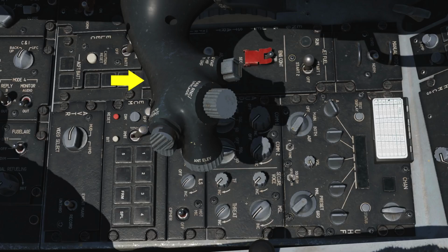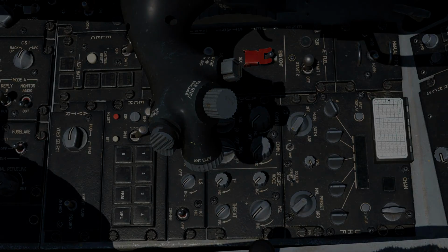HOTAS functions at the throttle include radio transmit switches, IFF interrogation control, a manual range and uncaged knob, radar antenna elevation, control wheel, a dogfight switch, as well as a speed brake and radar control cursor. In case of a deep stall departure, the pitch override switch allows you to command greater authority from the stabs to help get the nose pointed downhill so you can gain speed for control flight. The guards on either side of the switch allow the pilot to better grip it in case of inverted departure when he's hanging upside down by the straps.